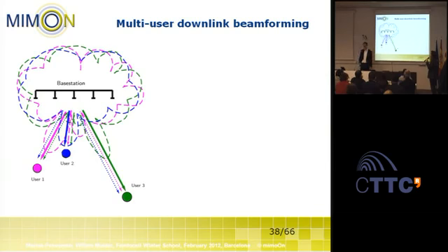No, this can be very naturally incorporated in our beamforming approach, and actually we have some work on this. We have a paper in ICASSP where we try to select. Of course, there's also a large overhead associated with CoMP transmission. If you have multiple connections to multiple base stations, there's an overhead for channel estimation and also routing the data. So you should only do this if you have a clear benefit. So we propose an integer programming approach where we try to optimize which connections to which base stations we should have.